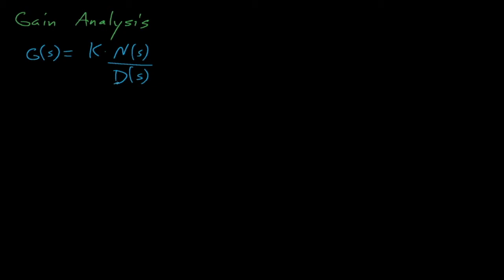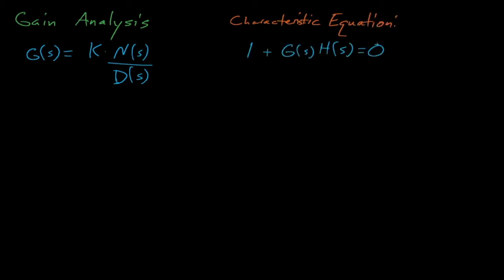As we've mentioned before, and will mention later, the power of a reactor can have a significant impact on the reactor's stability. For example, reactors are often unstable at lower powers because the system's power is just too low to generate any feedback. Recall the characteristic equation of a control system's transfer function, where the roots of this characteristic equation dictate the system's stability. Again, any roots in the positive real half-plane mean that the system's output will contain an increasing exponential term and will thus be unstable.